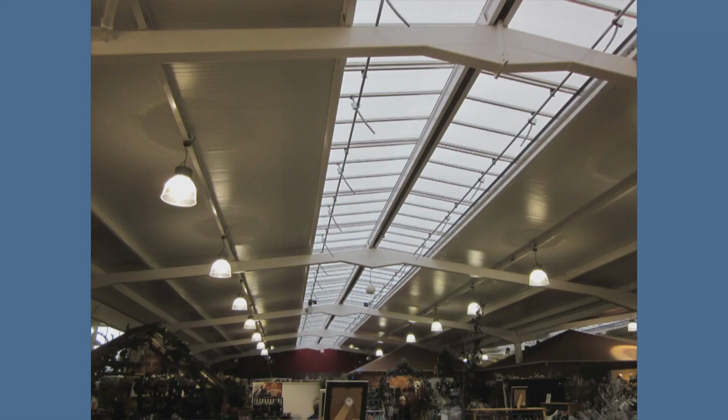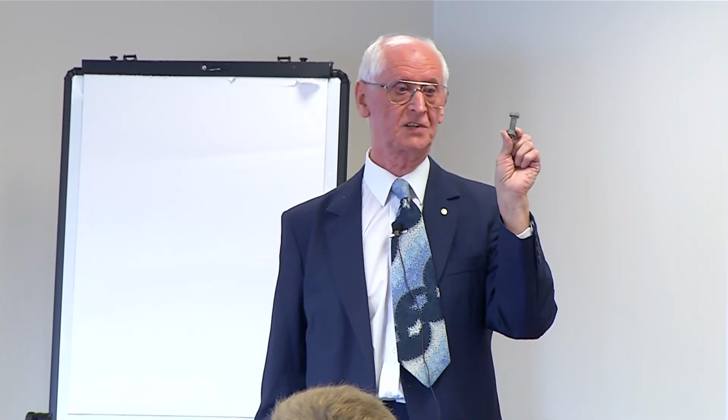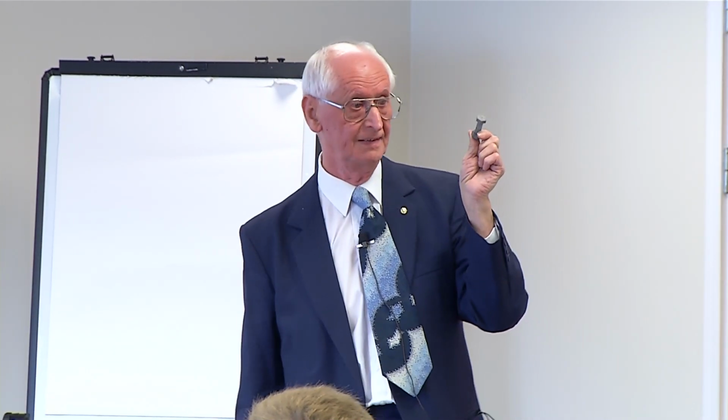And I come to these. This, as you can see, is a garden centre. Again, a large portal frame. But that portal frame has a critical connection here, as you can see by the strengthening. And that plate has just 4 bolts here. 4 of these. And that's all that's holding up a 20-metre span.